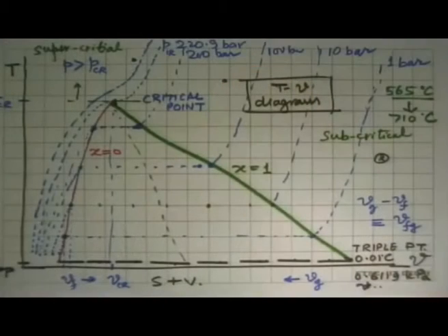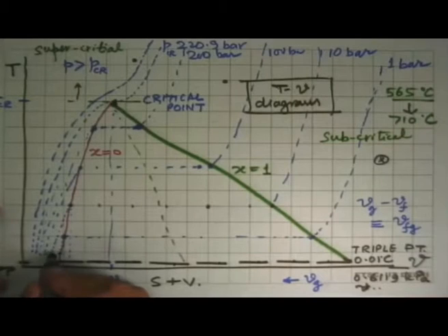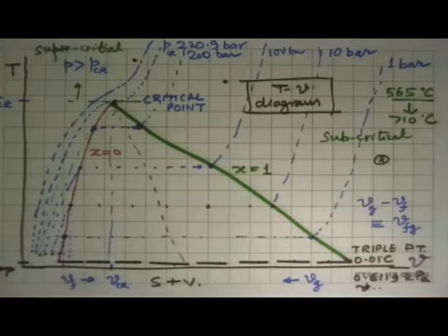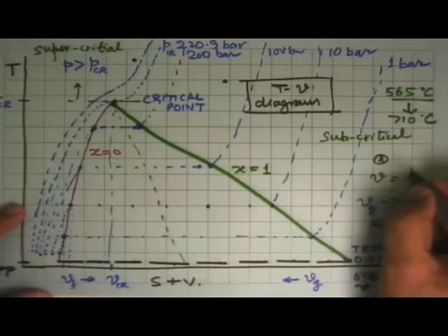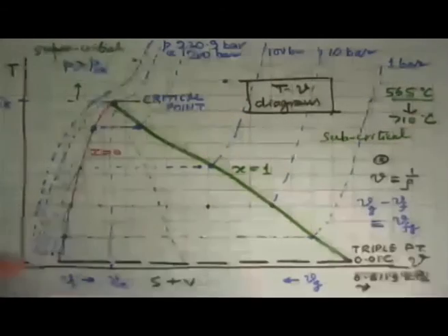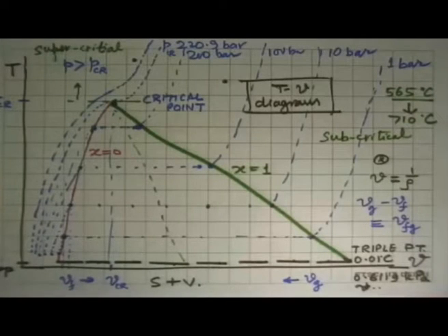Then there is another question. Why is the specific volume of liquid decreasing as we are increasing the pressure? Okay. The question is, why are these points going like this when we increase the pressure? Well, if you look at it the other way, by looking at density, when you take water and compress it, its volume goes down. It becomes denser, so density increases, and specific volume is 1 upon density. So you can see there that when you increase the pressure, the density has increased and the specific volume has decreased.